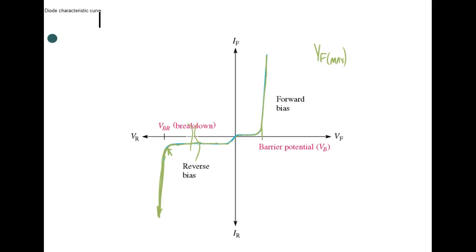Yeah, and that's not an average voltage, that is a peak voltage. So that means when we're trying to block V, we're going to be blocking V peak, not V average, V peak, right? You understand? And then sometimes in a full wave power supply, which we'll talk about, the diode actually sees peak to peak. So we'll have to make sure we get above that, probably at least about 150%.